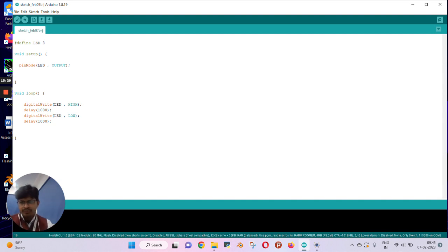Whatever value you want to put here, you can give. I want to glow our LED for 1 second, so I have written 1000 milliseconds here. And I want to turn our LED off for 1 second, so I have written 1000. Whatever value you want, you can change. Now the code section for our Arduino is completed.